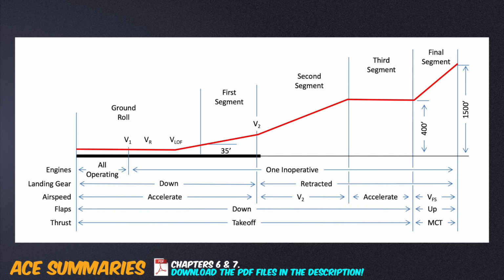A reduced thrust takeoff will use more trip fuel, and the reduced thrust means that the aircraft will spend more time below its optimum fuel consumption altitude.